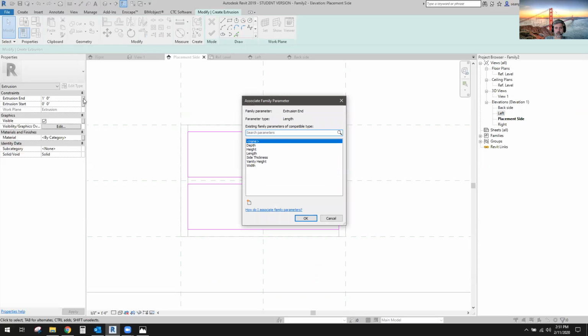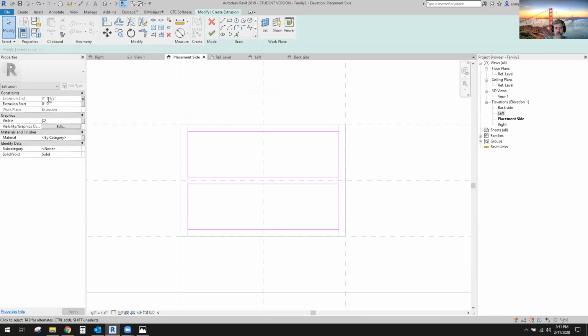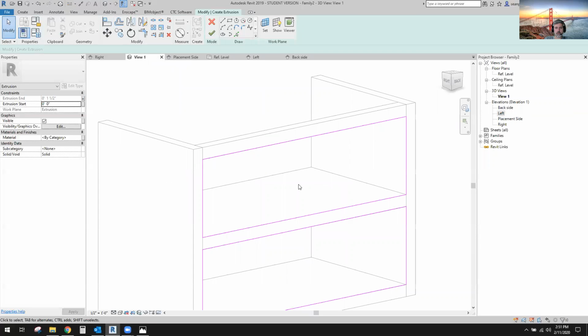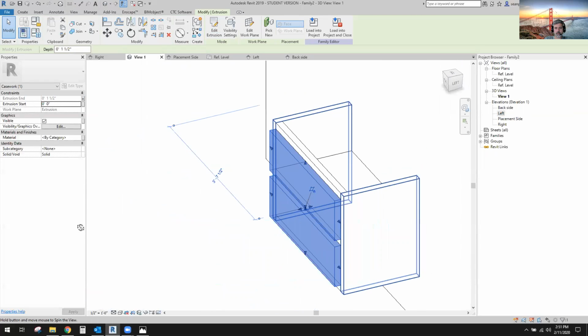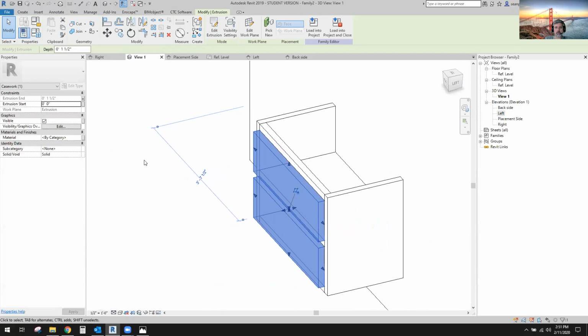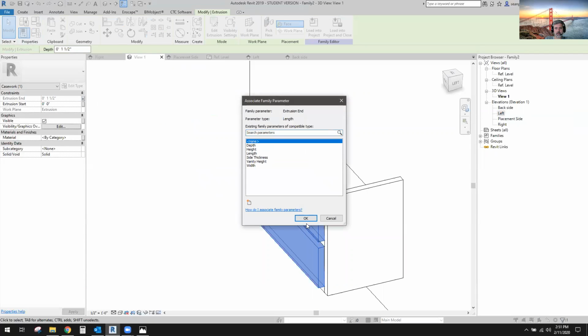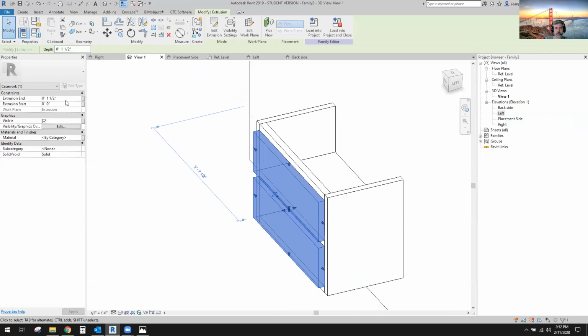I'm going to control that depth with the parameter here. So just hit this little box here, vanity or side thickness right there. Okay. Notice it put it in at that same thing right there. Okay. Now, I'm not sure which direction that extruded, so I'm gonna check that in 3D here after I apply it. It extruded in the direction I want, and I think that might be too aggressive. So let's go over here, say none, and okay, and we'll give this probably maybe let's say a 3/4 inch thickness here.